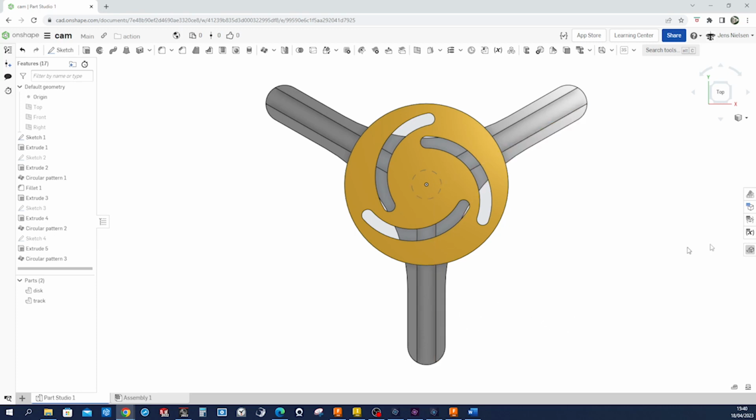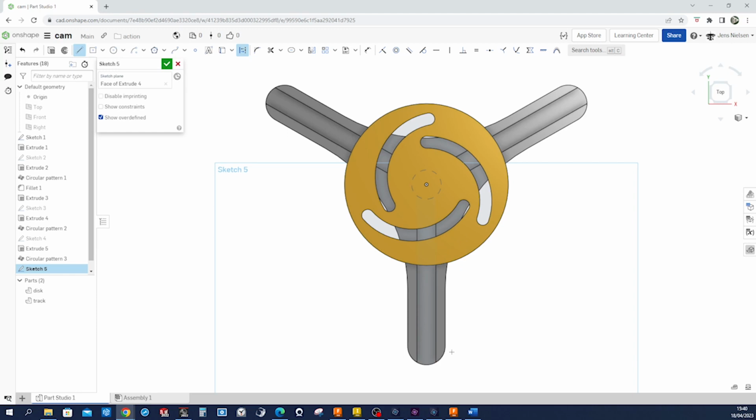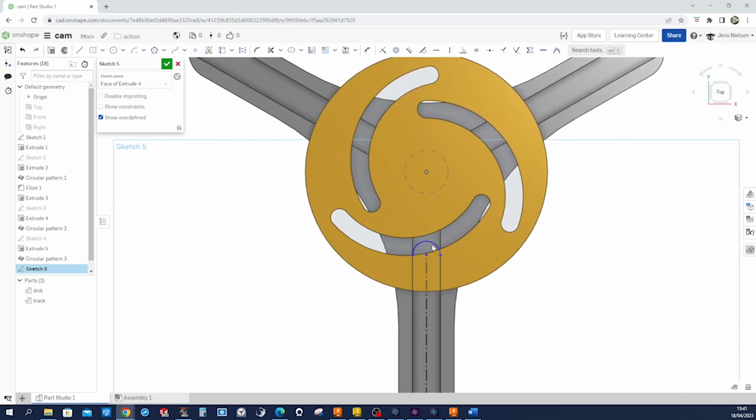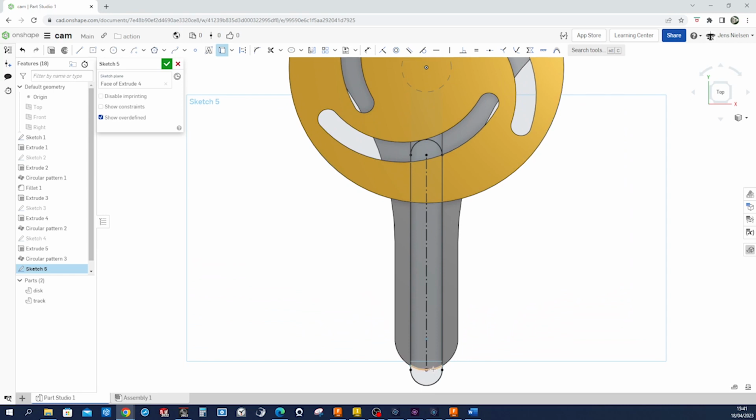And now define the slider here with the line on that face. Construction geometry, we can start here. Go over here. Make that again a slot. Accept that. Remove that dimension. Make that coincident here. Now let's take that out here and make that tangent to that edge. All right, and let's just finish that with this edge here, that extrusion.